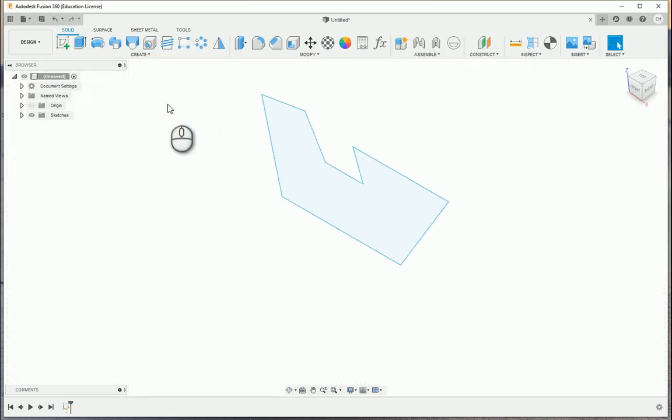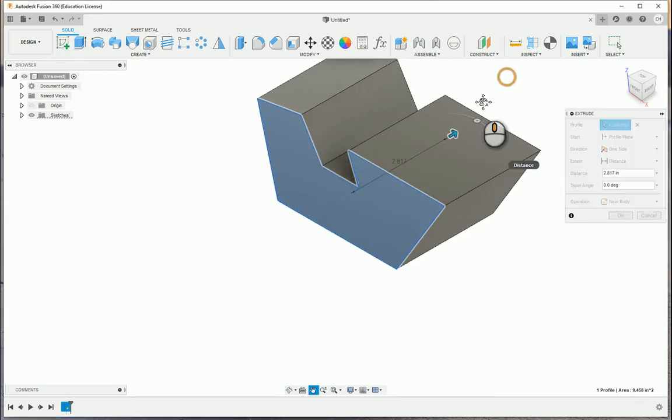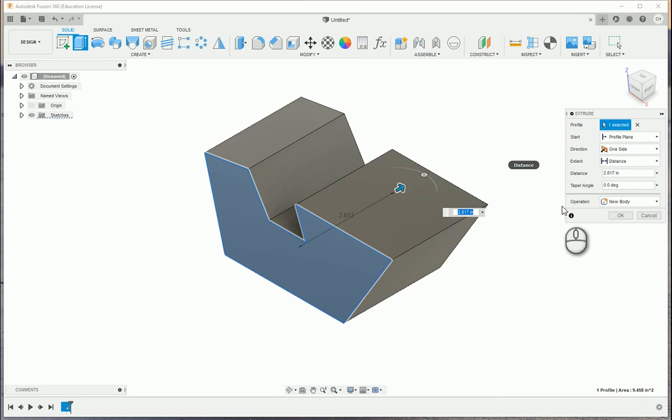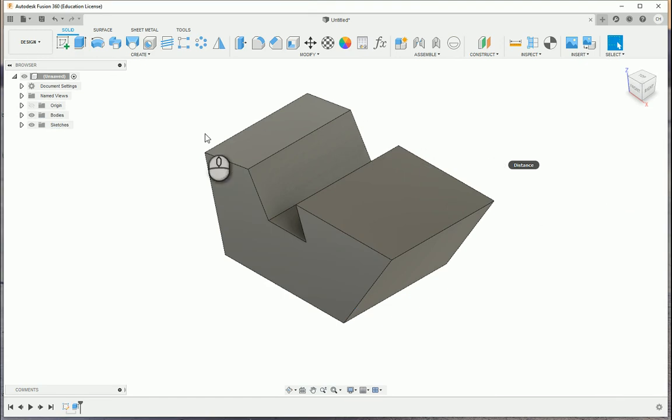They want us to finish and extrude the shape. They don't really define how much, so if you extrude the shape, you can see what kind of shape you get from it. We'll do 3 inches just for an arbitrary number. And this finishes out steps 3 through 8.